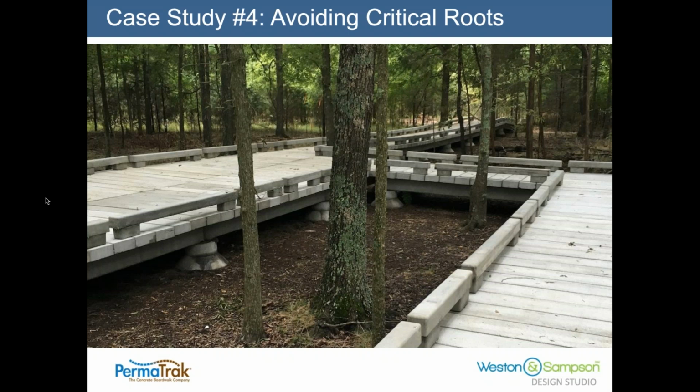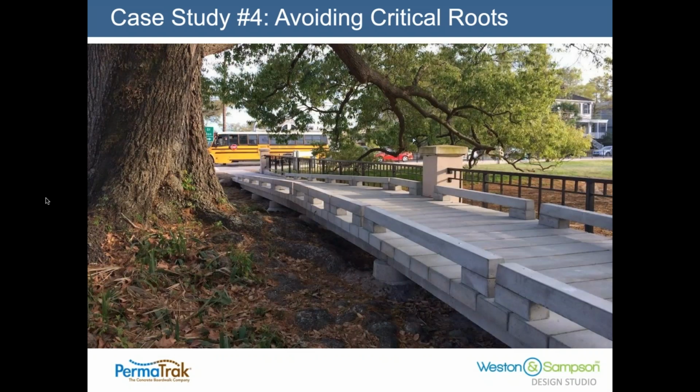And a boardwalk system like our system was used here, where the foundation system simply rests on top of the soil, and it could be moved in by hand. So the piers that you see there were set by hand. All of the components were set either by hand or by very small lifting equipment. This was all built from the top down on this example.